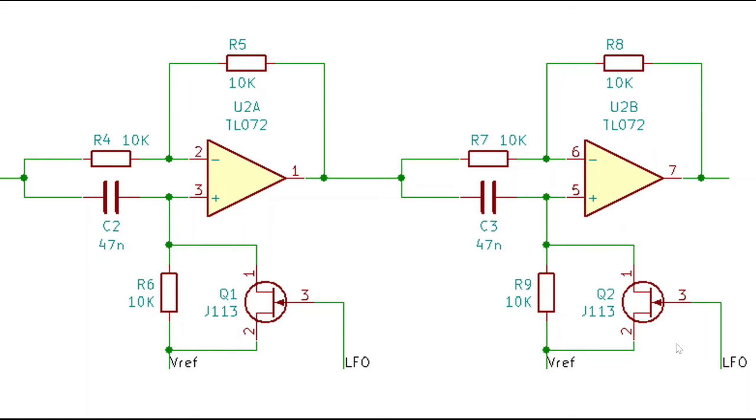there is a reason they say these JFETs. This is where I'm gonna finish with. There is a reason why they're using this. They're saying these JFETs should be matched, because then this change in the voltage is happening at the same rate. They don't vary widely, so you get a better sweep.